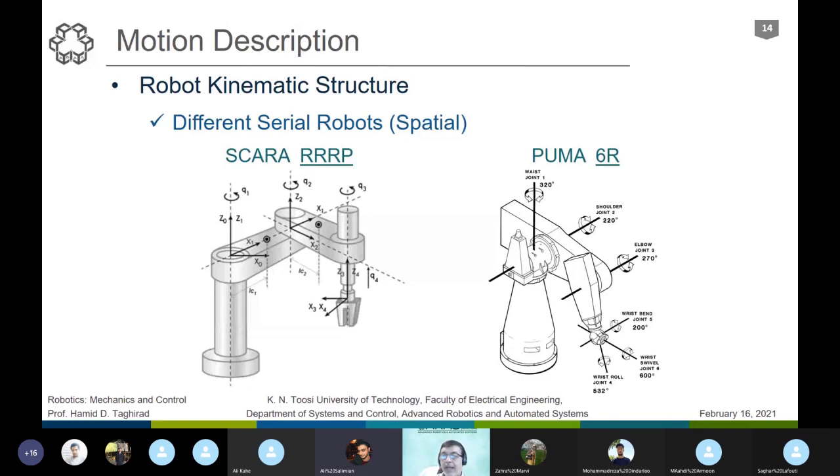Actually, when we have, for example, 3 actuators or 3 joints, I will discuss it in more mathematical aspect in the next chapter. But when we have 3 degrees of freedom in terms of actuators, in terms of the joints, it is quite clear that at the task space, at the end effector, we can only control 3 degrees of freedom of motion.